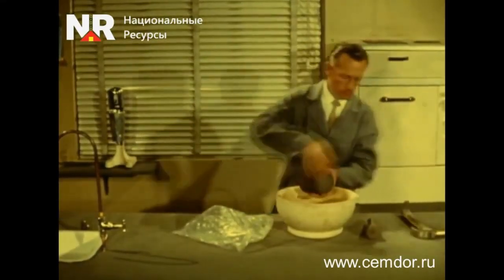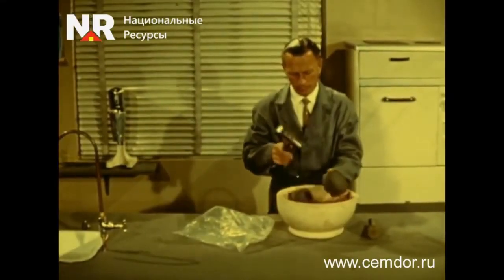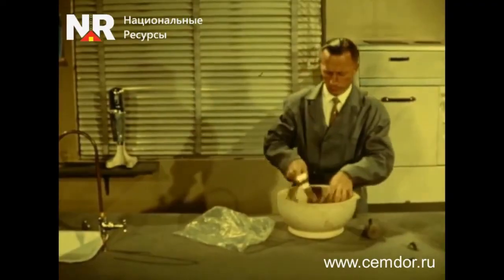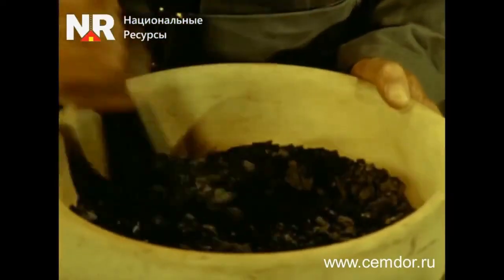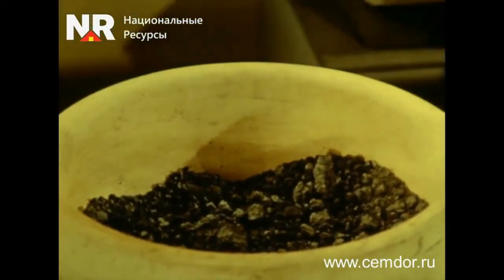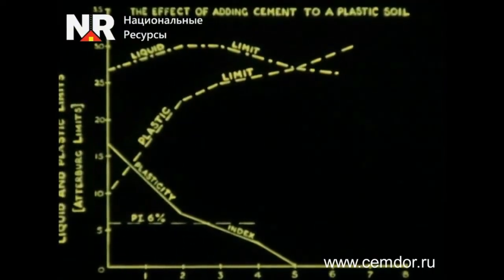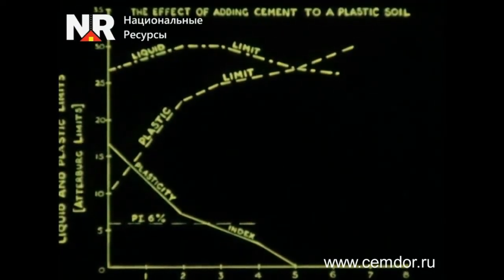The characteristics presented above are given for each soil composition containing different amounts of cement or additives. A small percentage of cement added to the original soil consistently improves its properties and allows for achieving the high performance required for constructing the structural layer of the road pavement. The results clearly demonstrate this: for stabilized soil, the plastic limit increases while the plasticity index decreases as the amount of cement increases.